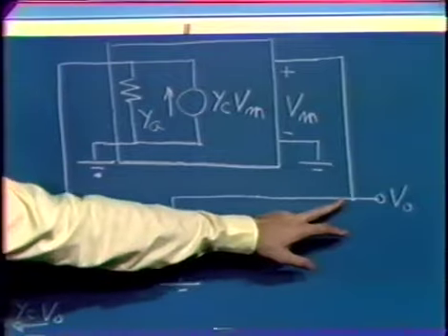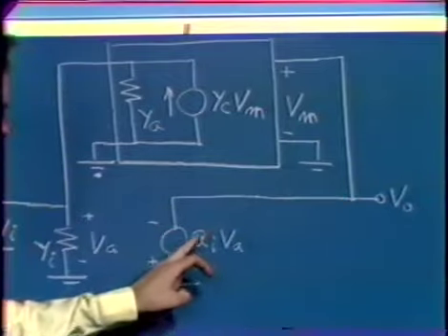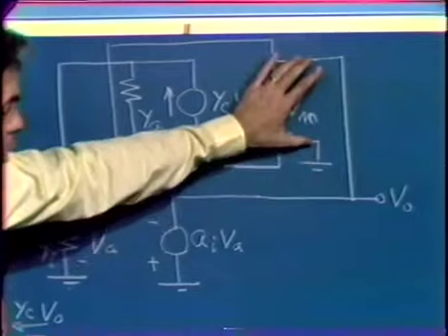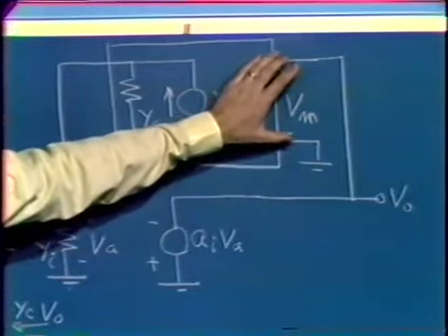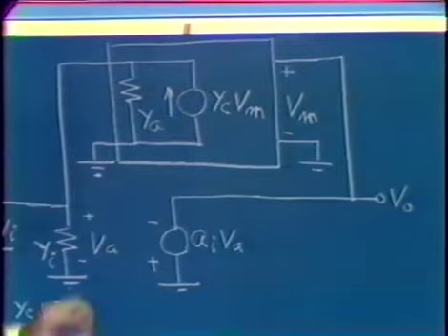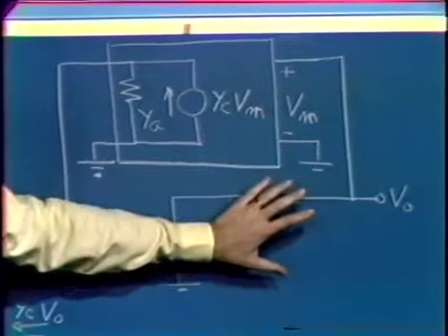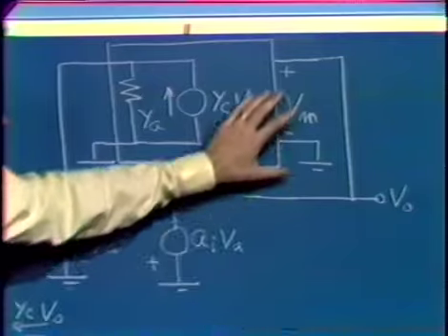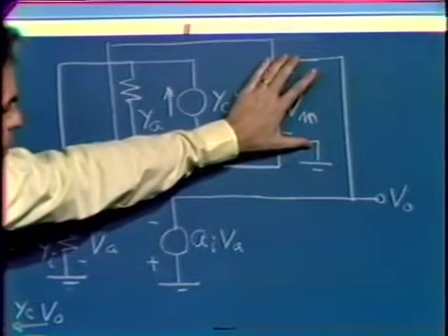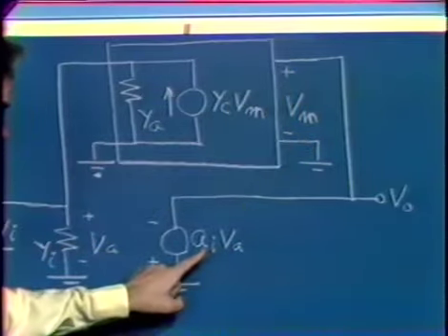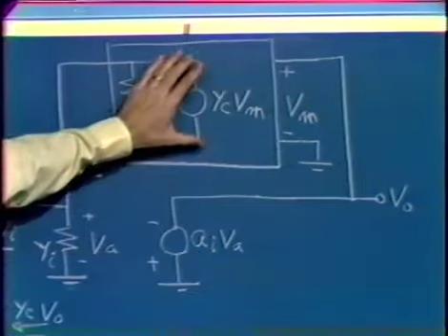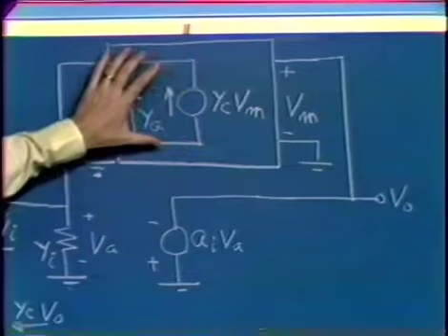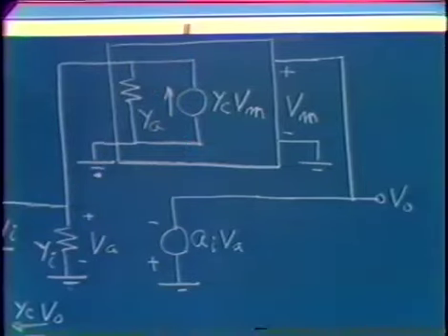At least as I've shown things, where we apply the voltage from a voltage source to one side of the two-port, we don't have to worry about parameters of the two-port at this side of the network. They can't really affect operation if this model is valid, since the input parameters on the two-port can't affect the voltage of this source.